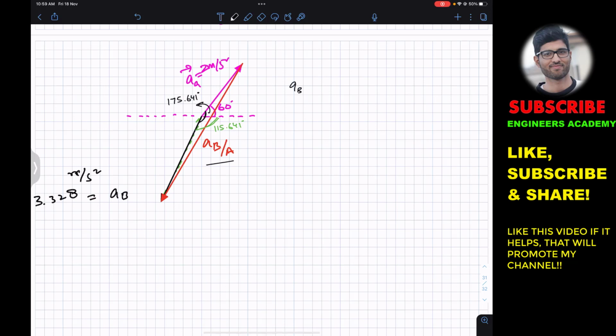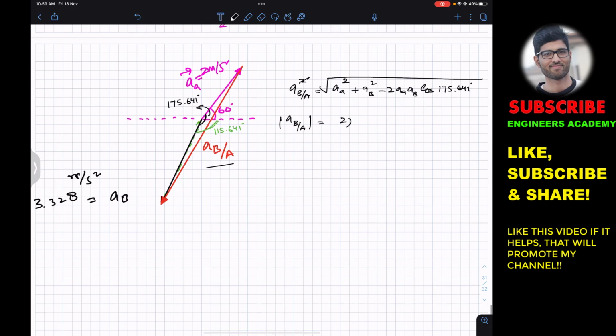Now we can find the magnitude of this ABA using the cosines law. So the acceleration of B relative to A magnitude square will be equal to AA square plus AB square minus 2 AA into AB cos of the included angle, 175.641 degrees. And if we take the square root on both sides, we will get ABA magnitude. Now AA is 2, AB is 3.328.